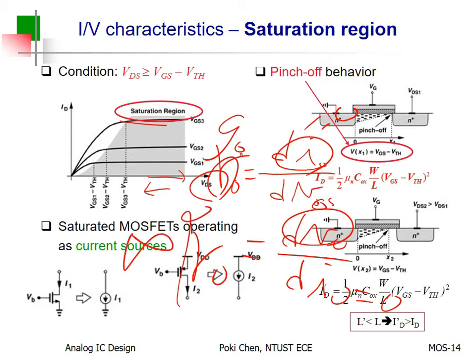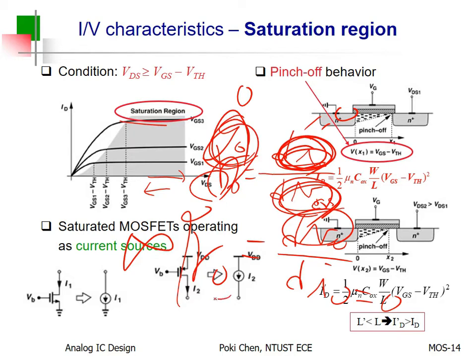On the contrary, how about GO? Yeah, dI over dV. So you change VDS, no change in output current, so you get 0 conductivity. Congratulations. That is what we need for a MOSFET. But nothing is perfect. According to channel length modulation, if you change VDS, ID will change a little bit. So you have some kind of conductivity, and it means the resistivity won't be infinite. No, it cannot be infinite. Yeah, it is finite. It must be finite.